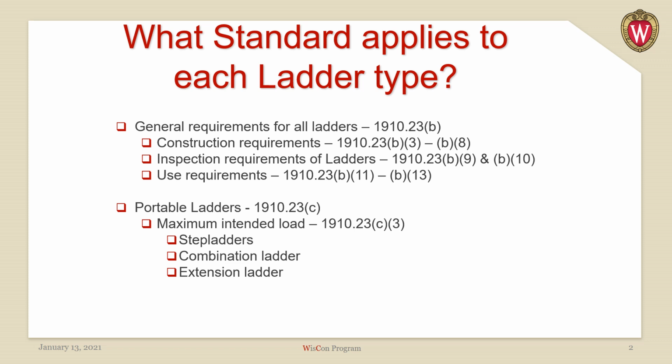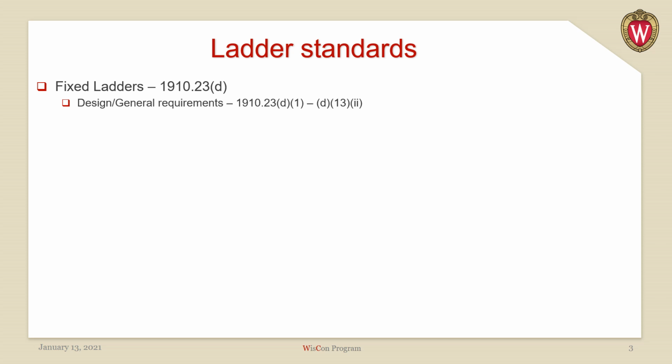That's an important aspect to remember when you're looking at your ladders and when you're selecting ladders. Ensure that the ladders you're using, whether they be step ladders, extension ladders, combination ladders, etc., are not being overloaded by equipment and individuals and so forth. So pay special attention to that and ensure that you choose the right types of ladders for the right types of situations.